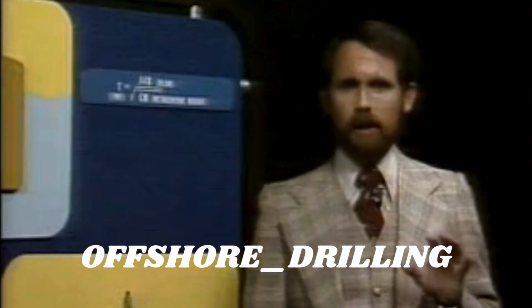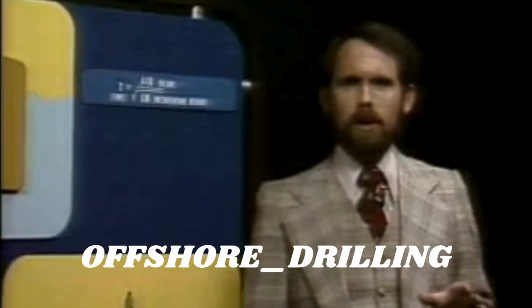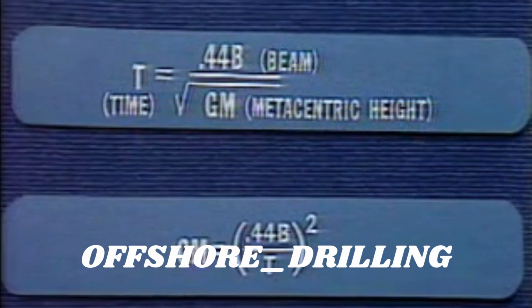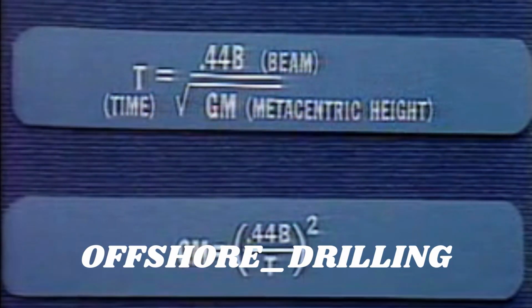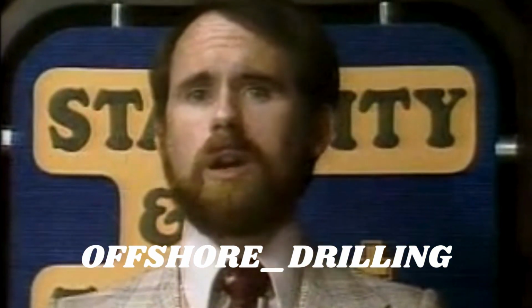Also, a ship with a very large GM will be more rapid and uncomfortable in its motion than one with a small GM. Turning the formula inside out, we find that GM equals 0.44B over T squared. We can use this version of the formula to calculate GM after we have timed the roll, and then we can compare this with the figures we get when we compute GM as we did earlier in Part 1. This is a good check on the accuracy of our calculations.